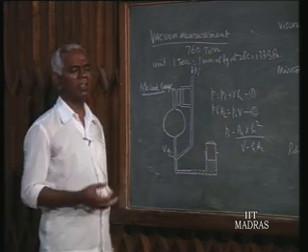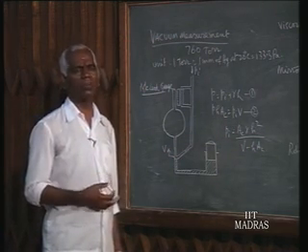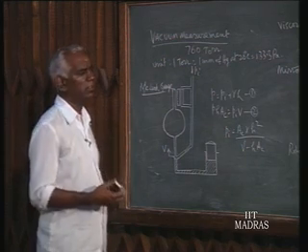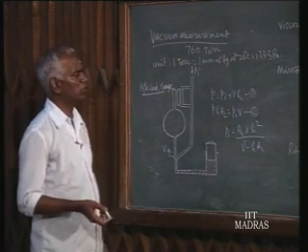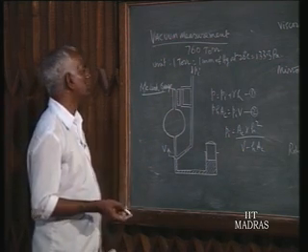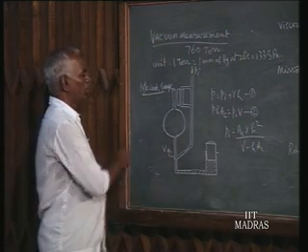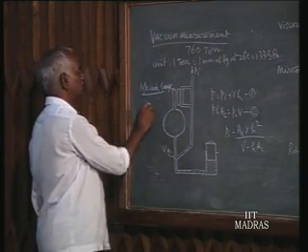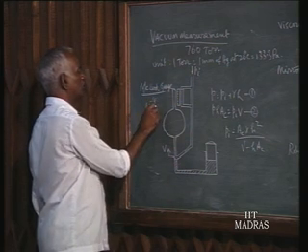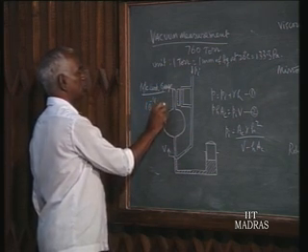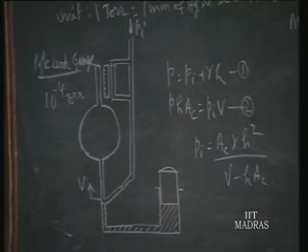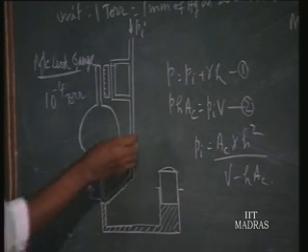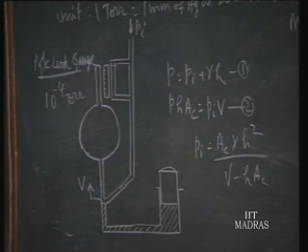So when we create vacuum, naturally we have to measure the vacuum, how much we have created in a chamber. Hence you find the vacuum measurement is also an important parameter. For calibration purposes, people go for this molecular gauge, which can measure up to 10 to the power -4 torr. It is mainly used for calibration because the measurement principle is based on Boyle's law.